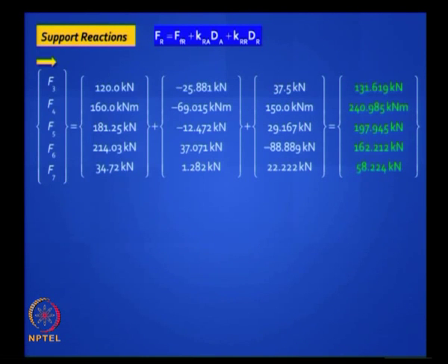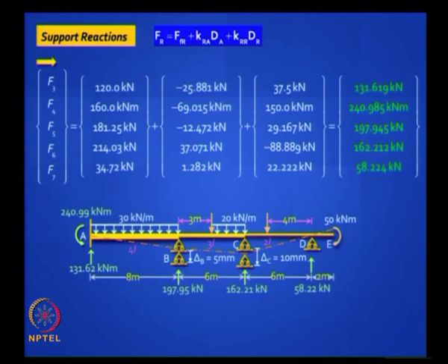Now you need the support reactions. This is where you have to look at the big KRA and KRR matrices which you generated in your stiffness, but we have done this in the conventional stiffness method. So this step is same to that, similar, there is no difference. So you should get exactly the same answers because only dA was unknown here, the rest we had derived earlier in the conventional stiffness method, and you will find you are getting the same reactions.